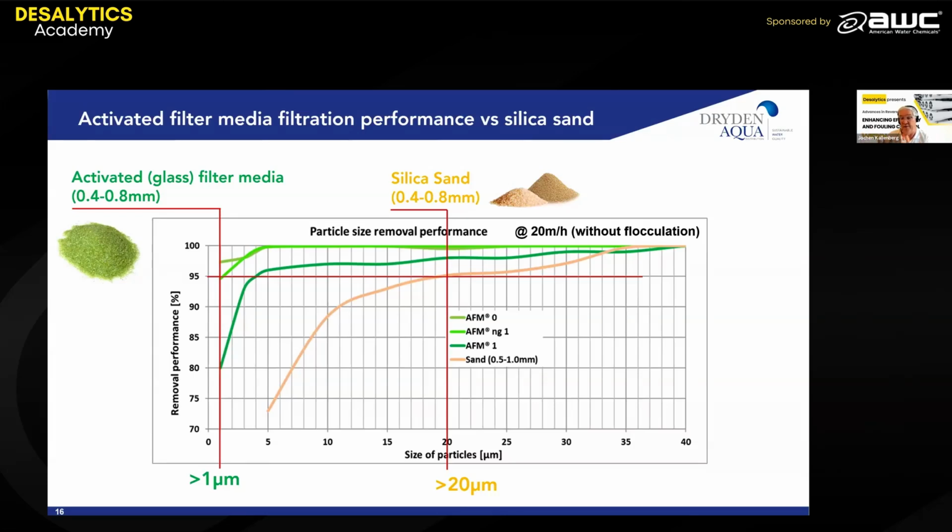That actually makes a big difference, especially in RO pretreatment, where you want to reduce the SDI or reduce the organic or inorganic fouling in your membranes by removing these fine particles to extend the runtime of your cartridge filter, not replacing them in the frequency you're doing it today. So here with our media, we dramatically reduce the exchange rate required for cartridge filters.